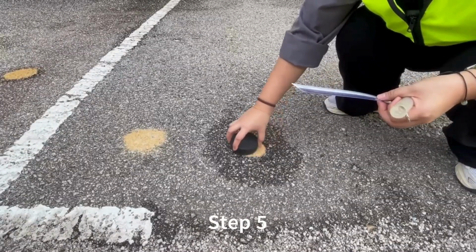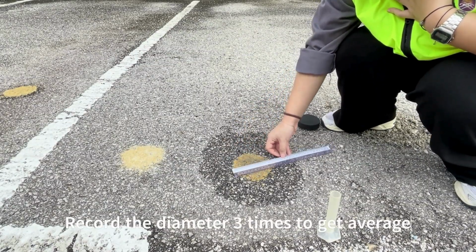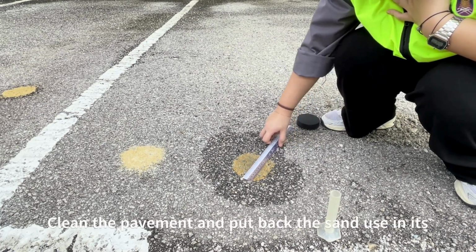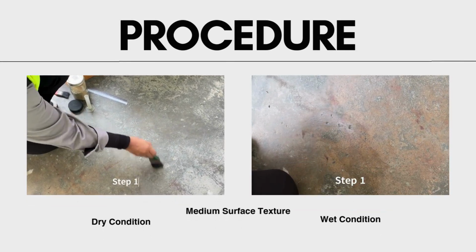Step 5. Flatten the heap of sand following counterclockwise. Step 6. Record the diameter 3 times to get the average. Step 7. Clean the pavement and put back the sand used in its special jar. Repeat steps 1 to 6 for sand patch, medium surface, dry condition.